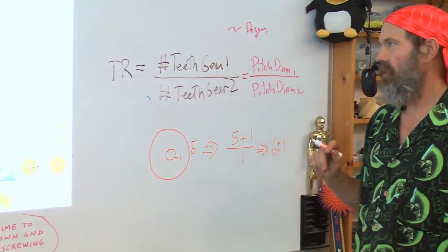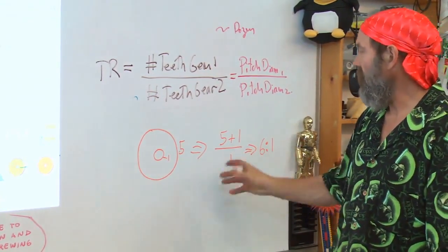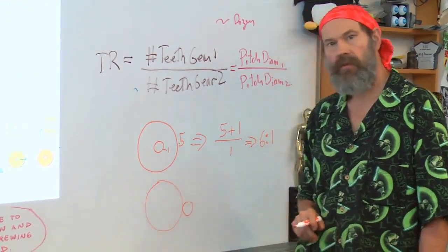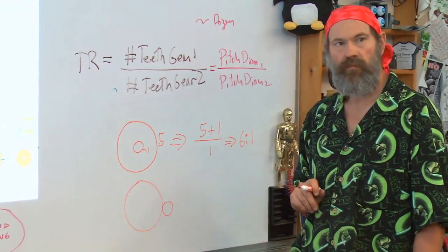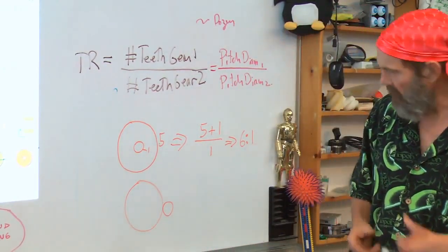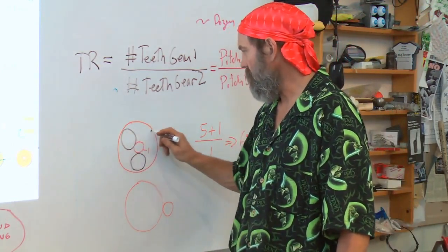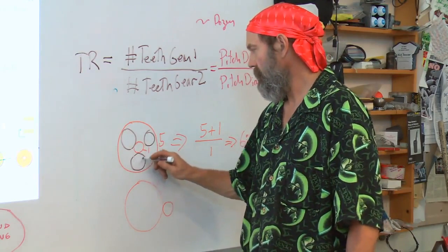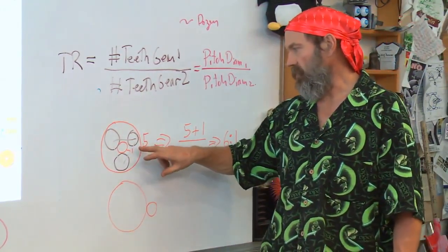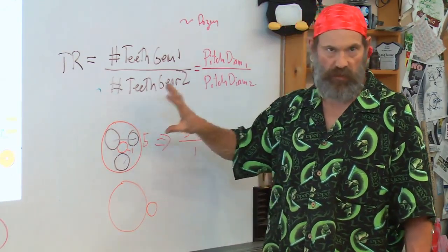And you may say to yourself, well, why is that any better than just doing this? Why would I want to go through all the complexity of having this machine here with these 3 planets? Well, the reasoning is, again, depending on what I'm going to hold fixed, the planet carrier or the ring gear, which ratio I get.